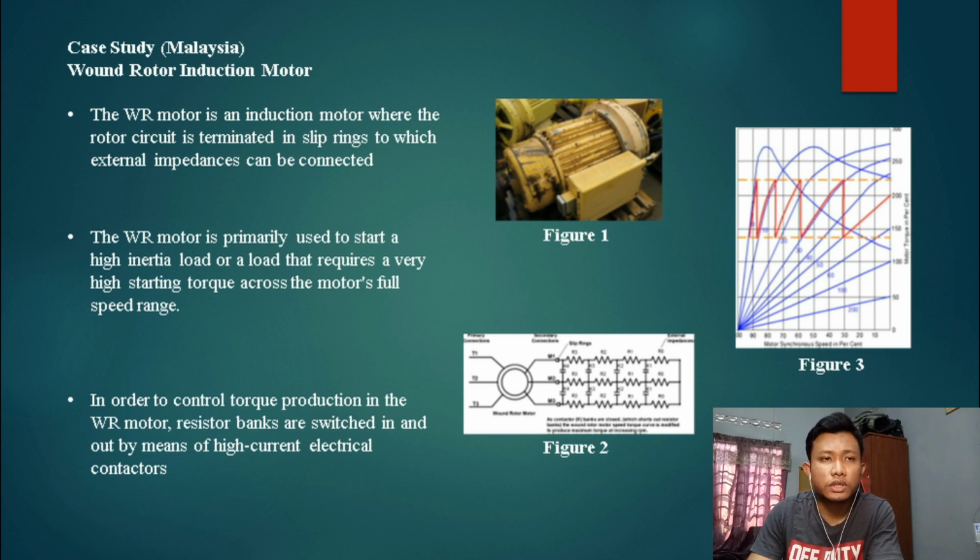the application starting torque requirements. In general, if the application operates below 50% speed for a high percentage of its operational cycle, it may be a good candidate for modernizing to a VFD as a way to save energy.